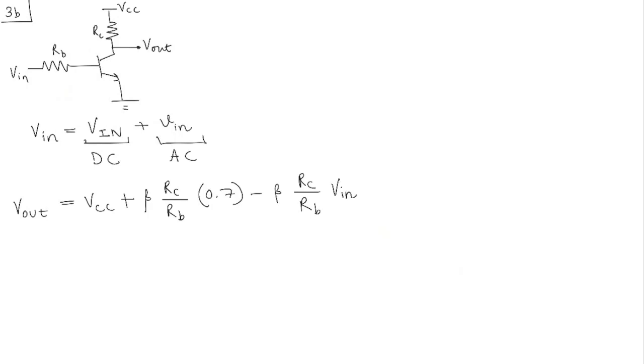Now what we are saying is, this V out is basically the collector voltage, isn't it? It is the collector voltage, and we know what the base voltage is, which is 0.7 volts when this is in active mode. What we want is this junction to be reverse biased, right? We want the base collector junction to be reverse biased. Now, what does that mean? That means that V out has to be greater than VB minus 0.5. And we know VB is 0.7 volts, so this has to be greater than 0.2 volts.